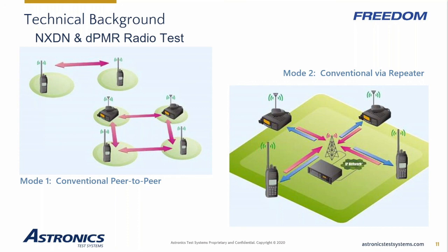The communication range is extended by linking multiple repeaters to cover larger geographical areas and connecting 2 sites through internet IP addresses or private data networks. When the user transmits, the signal is repeated to all sites, potentially even covering different parts of the world. Each site can have its own single frequency pair, although when the repeaters are linked, all pairs are used simultaneously for a conversation.